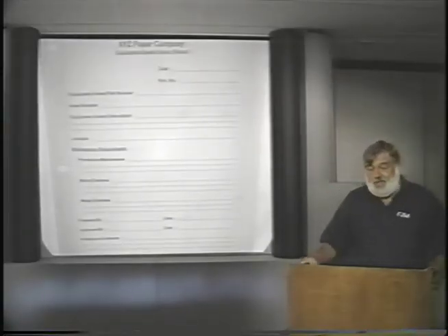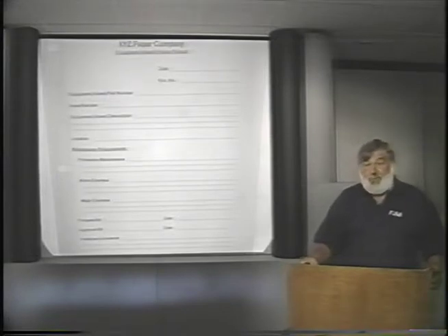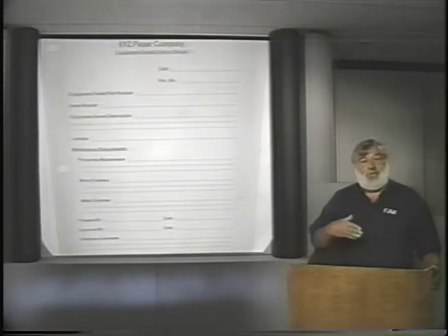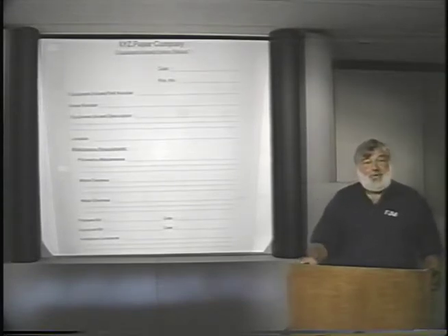In the upper right-hand corner, we have the date that this equipment record was actually developed and a revision number for that equipment. The revision number is going to be key in terms of tracking engineering change notice requirements. If you are just going to start an engineering change notice system, then my recommendation is start off with revision A, and then as we have engineering changes introduced for an asset, you could change that to revision B, C, and so forth. Now continuing down in the middle of the page, we have what we call maintenance requirements.